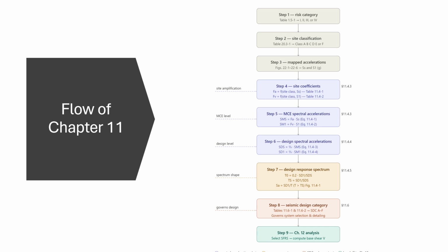So you have your site coefficients, which is kind of how your site is going to behave. And then you have your accelerations, which is how fast your site is going to accelerate under seismic excitation. This depends, again, on location. And then you take your design accelerations from your spectral accelerations, and then you have the movement values you're going to design your structure for.